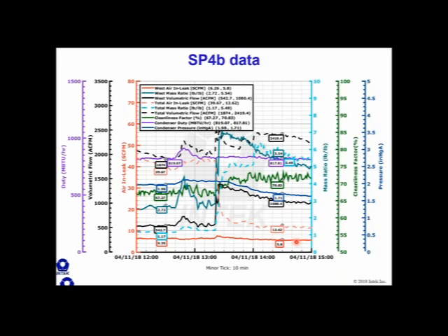They had some other leaks that were identified, some on the water box joint. There was a significant leak on their vacuum breaker. There were some other smaller leaks on some other valves. I don't remember which all ones were, but the big ones were on the water box and vacuum breaker, I believe. So there's some remaining air in-leakage, but they fixed the big one here, and now their air in-leakage is low.